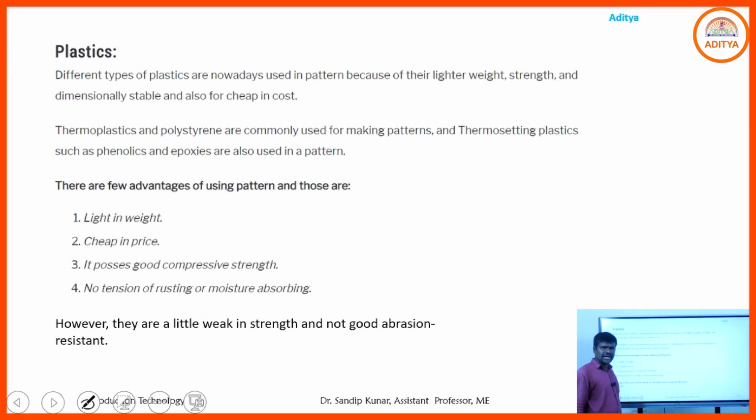Plastics. Today we use plastic material for preparing patterns, because plastic as a pattern material has lighter weight, it has strength, and it is dimensionally stable, meaning it produces good dimensions. Also, plastic is easily available in the market, and at present the cost of plastic is also low.